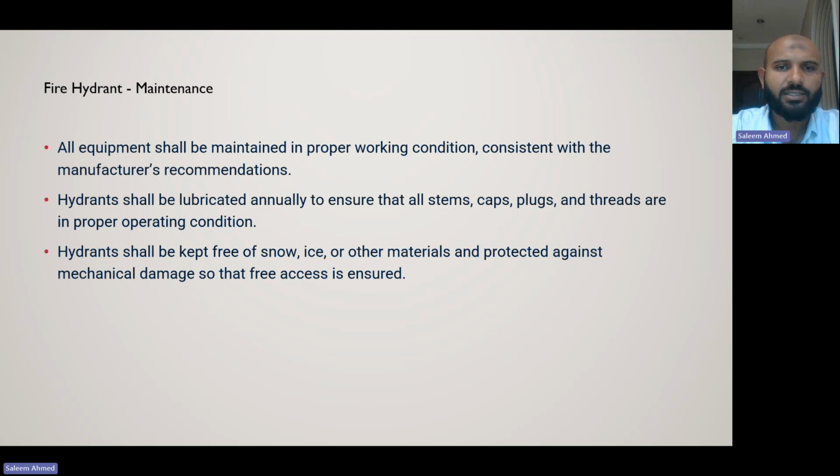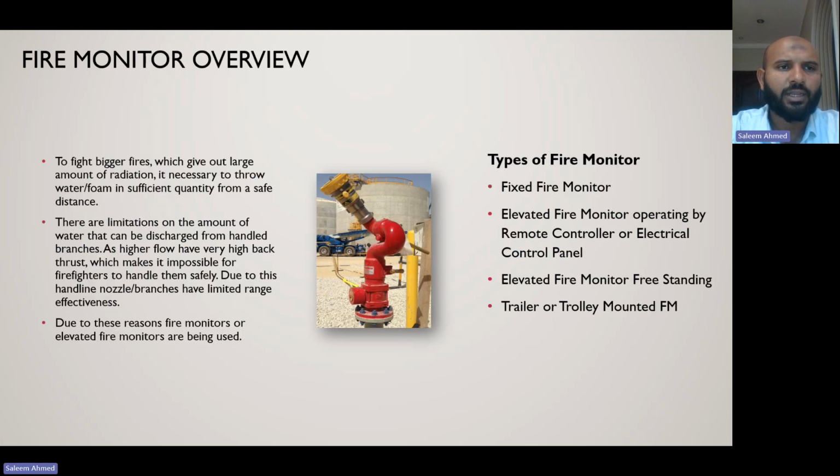Fire hydrant maintenance. So hydrant shall be lubricated annually, to ensure all the stems, caps, and threads are in proper operating condition. Hydrant shall be kept free of snow, ice, and other material, and protected against mechanical damage, so that free access is ensured. All the equipment also has to be maintained as per the manufacturer's recommendation. So moving next to the fire monitor.